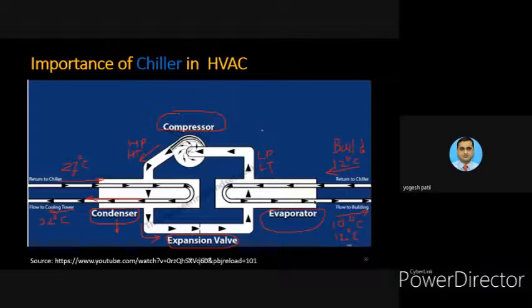So this is a basic idea of this particular core part of the chiller. The compressor gives high pressure, high temperature vapors to the condenser. The condenser converts those vapors into liquid form. The liquid refrigerant enters through the expansion valve into the evaporator. The evaporator plays a very important role. Some of the vapor part is again discharged to the compressor, and it also provides a cooled water supply to the whole building, actually not directly, but it provides to the air handling unit, and after that it is distributed over the building.